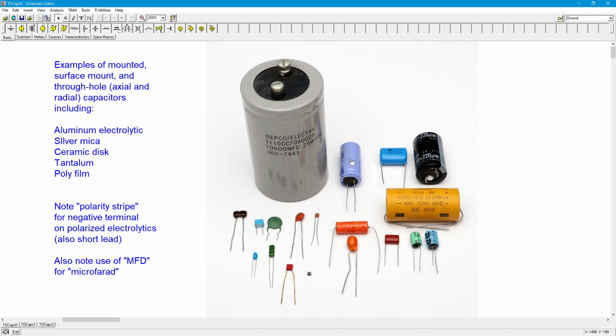And on modern electrolytics, at the top, you'll often see a little crosshatch, which is a sort of pressure relief. What will end up happening is these things will overheat, and that pressure release pops open a little bit. If it didn't have that, like old style caps didn't, this thing would literally blow up.